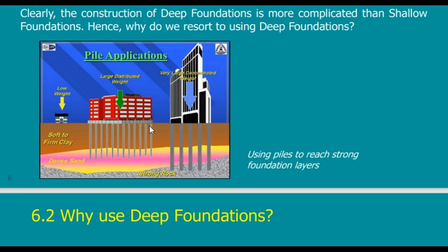using shallow foundations is not adequate. You will find this when you discuss your coursework number 2, that it is not adequate. So what should I do? I should use piles. In this case, I will take my piles to penetrate the soft soil on top and go to the strong layer below.